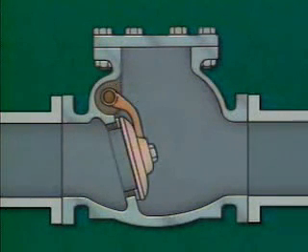Disc slam can damage the disc and the seat and result in leakage around the disc. For this reason, swing check valves are generally not used in applications where intermittent flow is common.